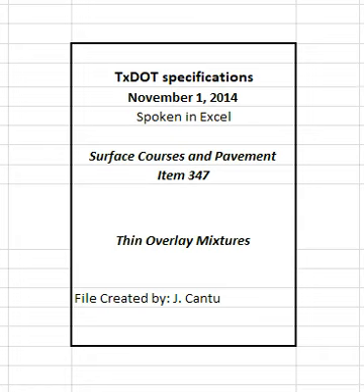4.4.2.2.3 Hamburg wheel and overlay testing of JMF1. If the contractor requests the option to have the department perform the Hamburg wheel test on the laboratory mixture, the engineer will mold samples in accordance with Tex-242-F to verify compliance with the Hamburg wheel test requirement in Table 7. The engineer will perform the overlay test and mold samples in accordance with Tex-248-F to verify compliance with the overlay test requirements in Table 7.